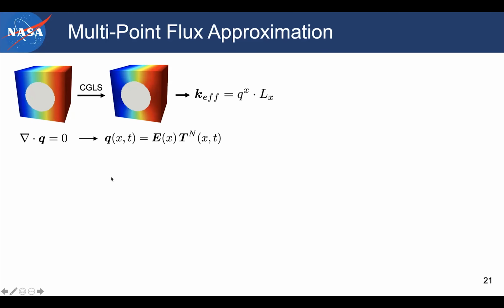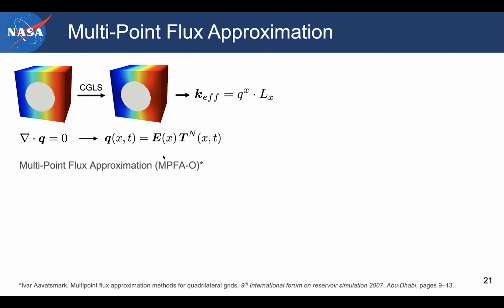The way that we approximate the fluxes, and linearly relate them to the temperature at the nodes, is by what is called the transmissibility matrix. And this is what the MPFA, the multipoint flux approximation, is about. A similar approach is used for the elasticity as well.